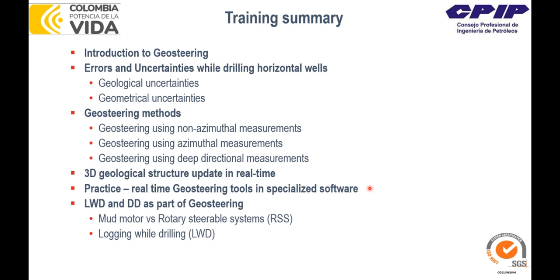And also, to support all this geosteering theory, we did a review of the LWD and DD technologies, logging while drilling and directional drilling, and we also touched a little bit on measurements while drilling. It's really important to refresh this part because the geosteering engineer has to be very familiar with the technology, so he can communicate with the directional driller and the logging while drilling engineer, and he can understand all the data which come in from all these sources.